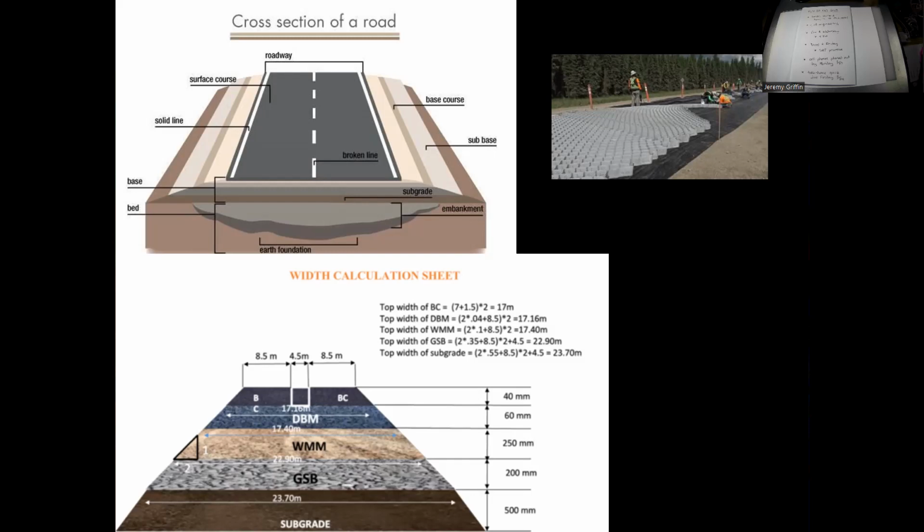Okay. And then what material is actually used for the top layer? It's actually asphalt concrete, which is a different type than Portland cement concrete, although you can use Portland cement concrete too. Each one has its own advantage. Asphalt is quieter, more rubbery, and easier on tires. Portland cement concrete, on the other hand, lasts longer, is more durable, and needs less maintenance.